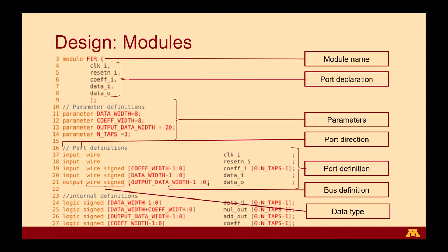Verilog by default has an implicit definition. So even if you have small typos in your code, it will think of it as a new variable, and it will try to work along with that, and it assumes that it will be a 1-bit wire design.